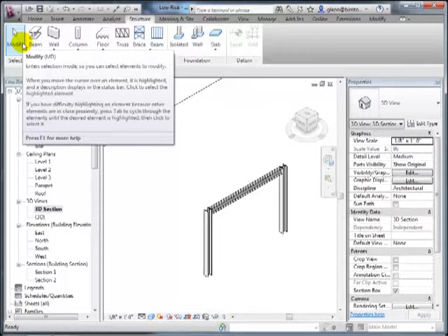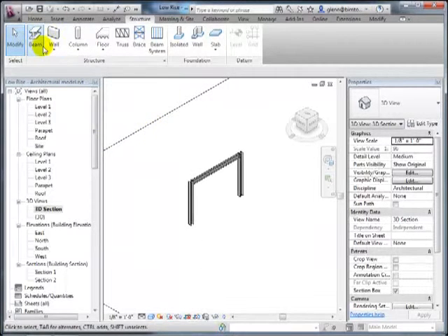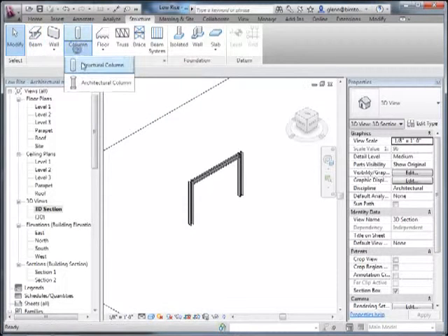it's like yes or no, because you're really placing them in whatever view makes the most sense. One of the hard things about placing beams in particular is that when we look at plan views from an architect standpoint, we're often looking at a cut plane that's halfway through the floor and then looking down. So one thing that confuses people is when you place beams, you're typically placing them above your head. So it's just a little bit confusing to people. So we could do that same exact thing that Reem was talking about. Let me put a few more columns in here.